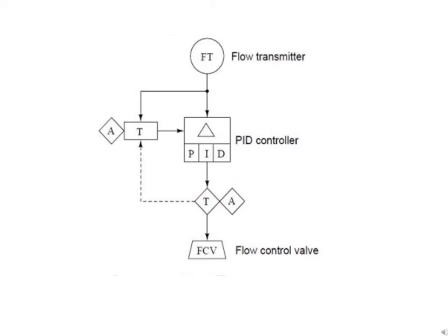Showing even more detail, the following SAMA diagram indicates the presence of set point tracking in the controller algorithm, the feature that forces the set point value to equal the process variable value anytime the controller is in manual mode.